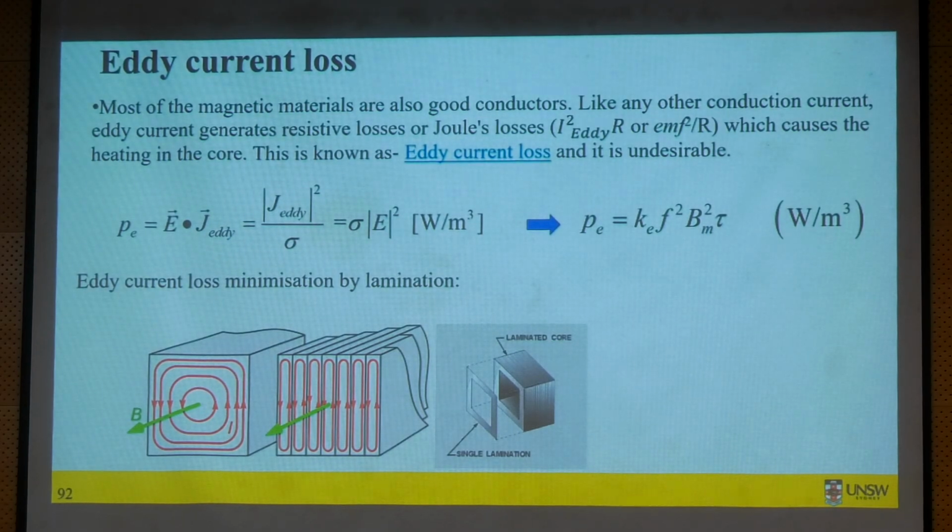So those harmonics may not rotate at the same speed as the synchronous speed. Okay, so because there is a difference in the speed between the harmonics and the rotor magnet, there could be eddy current loss in the magnets.